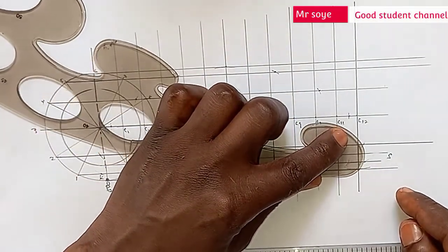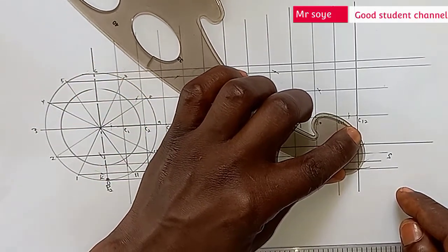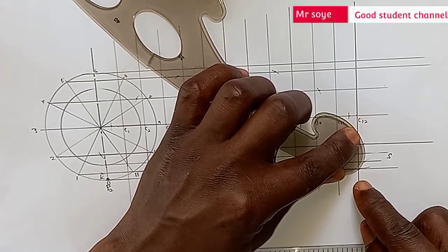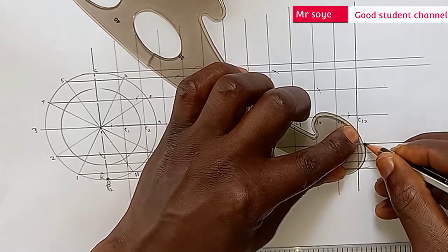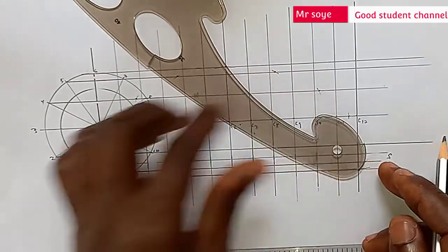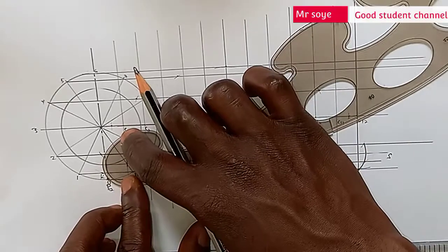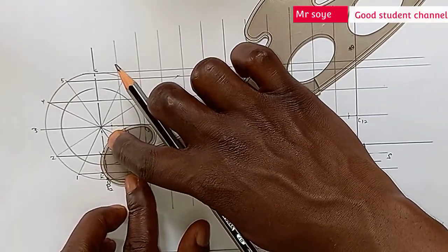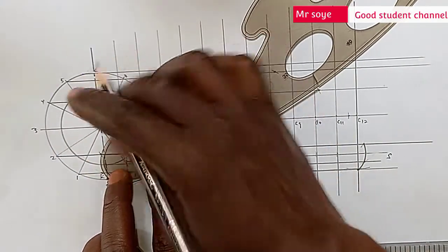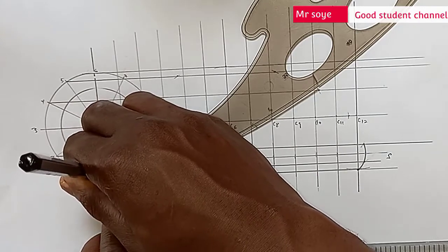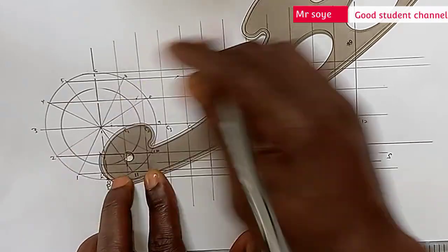That is, set the French curve so that it will be combining 3 points together, touching 3 points. So once you set it like that, as you can see, until you get a very perfect fit, once it joins 3 points, okay, I think I got it here, then join together. Then use that same side for this other side too. Use it for this other side. As you can see, good.